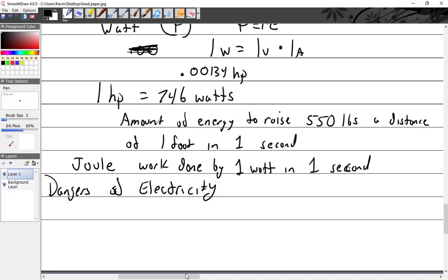One of the jobs that I really enjoyed the most was I did a lot of non-destructive testing work using a magnetic particle machine. As I mentioned before, you basically take a crankshaft or some component and put current through it, and I'll turn it into a magnet. I'm going to show you all this stuff when we get our machines working next semester. But so I'm putting current through the crankshaft.